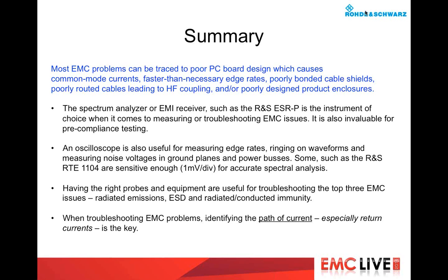And what I find is the best tool is a spectrum analyzer or EMI receiver, such as Rohde & Schwarz's ESR-P. These are really the instruments of choice when doing troubleshooting, because it allows you to see at a glance the overall harmonic emissions spectrum.